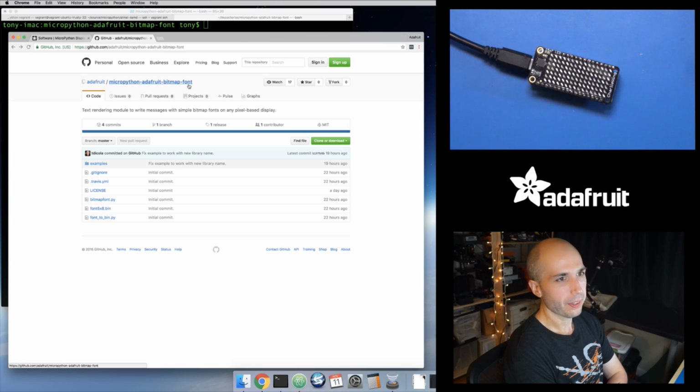And so it's real simple. It's based on the GFX library, which is a library in our Arduino world, and that's kind of the base of all of our graphical displays. So things like Arduino LCD shields or TFT shields, even little OLED displays that you might use with Arduino, all of those use this GFX library, which has built in line drawing, circle drawing, font rendering, drawing text on displays, and has a really simple 5-pixel wide by 8-pixel tall font.